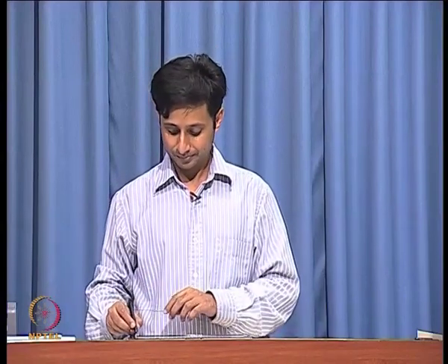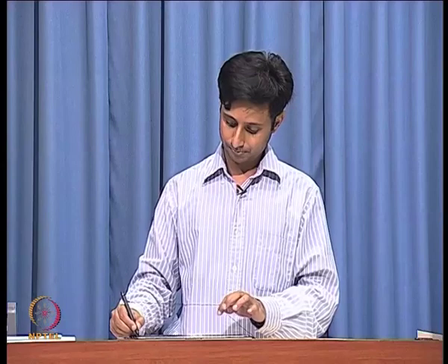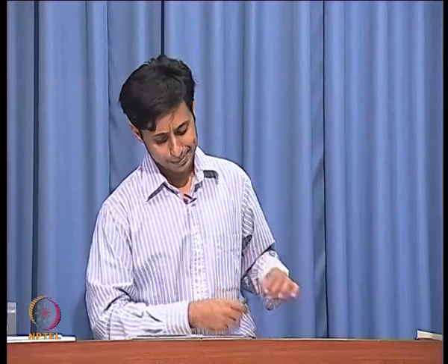What is an independent capacitor? In our example circuit, we have got CL and CDB parallel to each other, they are not independent. Okay. You can club them into one whole thing, and that will give me one pole, right. So, that is why I said independent capacitor. Okay. So, we have got all of these poles,